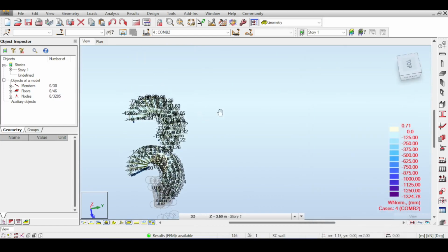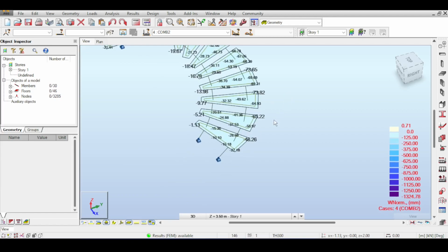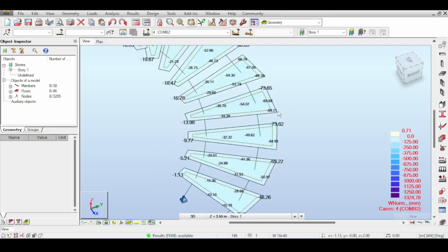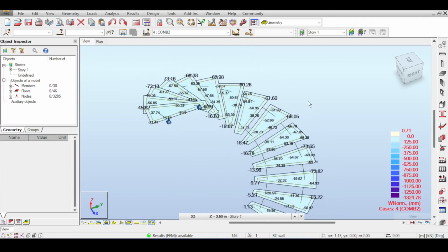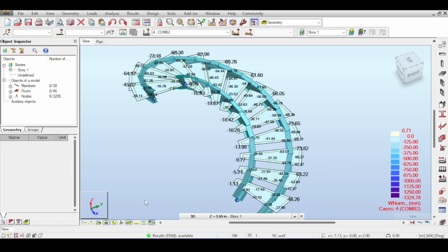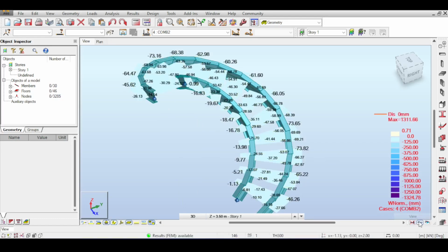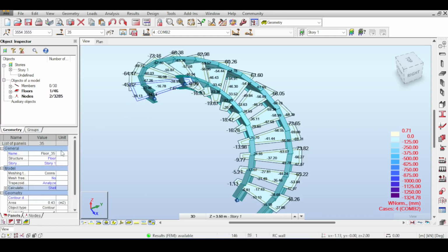The second thing here is for the steel staircase. So let's take a look at this mess. This is bad. You have 60 millimeter and 70 millimeter and whatnot. This is really bad. But why is that? Well, first of all, my beam is a placeholder and it's a big beam, so I was expecting it to be able to hold itself. But it wasn't. So this came as a surprise for me, to be honest. Why? I think the reason is that those plates are really heavy. They are made out of thickness 10 steel.